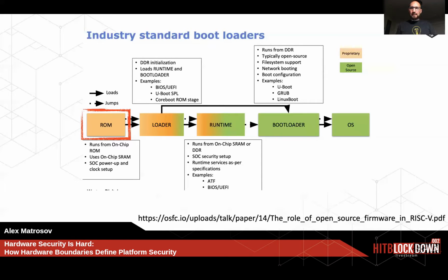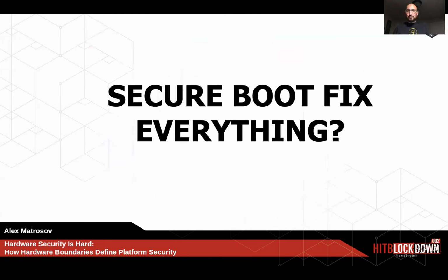In this case, I would say it is a dangerous place, because if this code is not formally verified and is still written in C, it's kind of difficult to believe there are no issues there, right? There's also the complexity of support. For example, if the device breaks, we need to understand what happened and actually make a recovery. Usually this kind of ROM can unlock serial, UART, or JTAG, and it creates additional attack surfaces. So secure boot fixes everything, right? In this case, it is not really true.